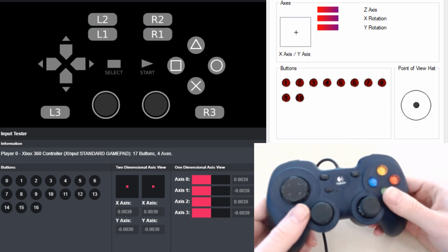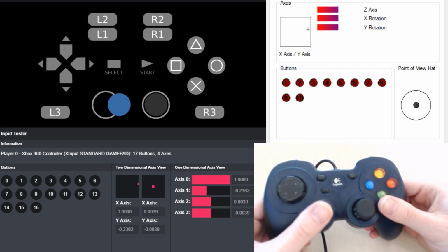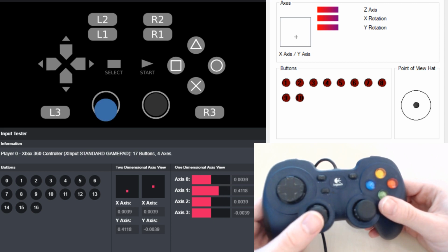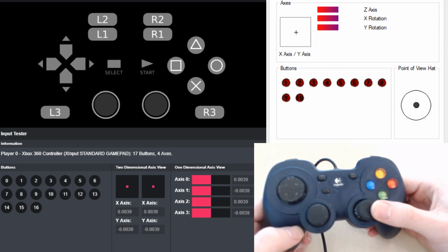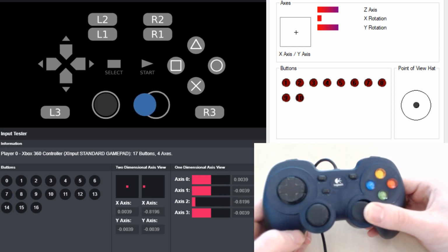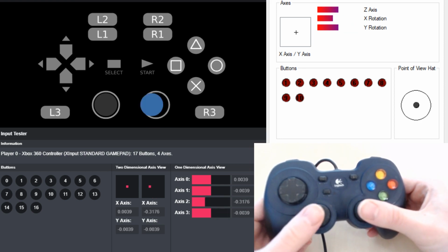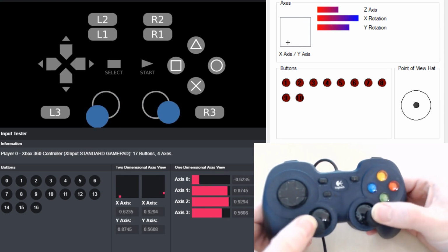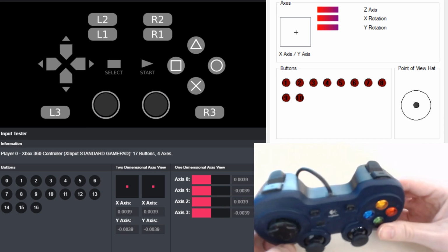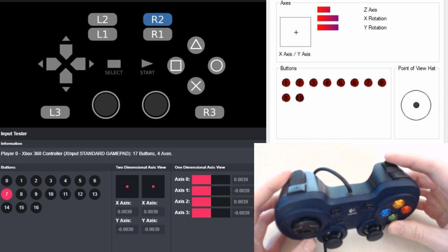In contrast to push buttons, analog sticks or triggers provide a continuous value somewhere between a known minimum and a known maximum. Therefore, an analog trigger can, for example, be pushed down 25%, 90% or any other fraction. This obviously contains more information than a simple push button, so it's not just one bit. But in the end, we are still talking about digital computers, and these machines exclusively process zeros and ones. Keep in mind that these two digits are internally represented by two different voltages. A low voltage is interpreted as a 0 and a high voltage as a 1.